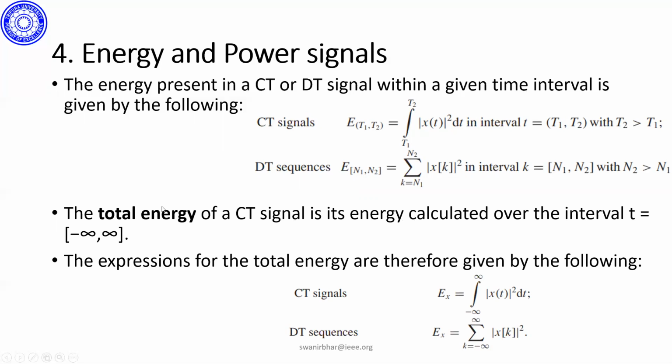If the signal is continuous and varies from minus infinity to plus infinity, you cannot calculate the energy. If you cannot calculate the energy, you can consider the signal periodic and take the signal in between. Like for a sinusoid, instead of taking it from infinity to infinity, which is very troublesome to calculate, we calculate the power for one cycle, which we call average power. You might have seen in your basic electrical engineering courses that we take average power, root mean square, where everywhere we use one particular cycle.